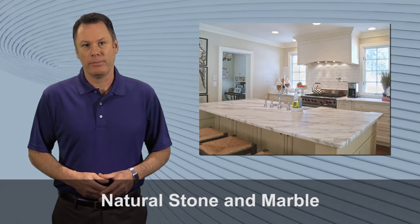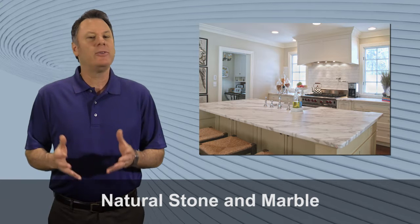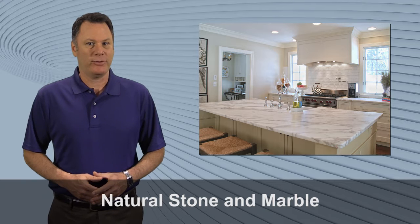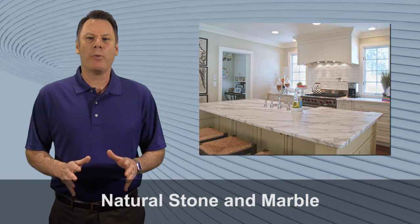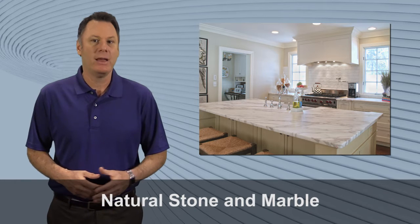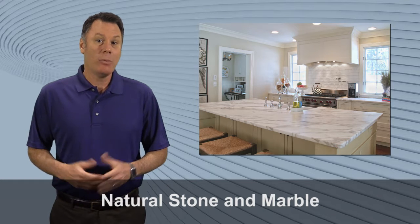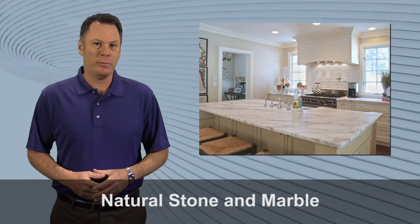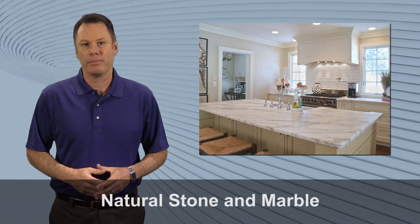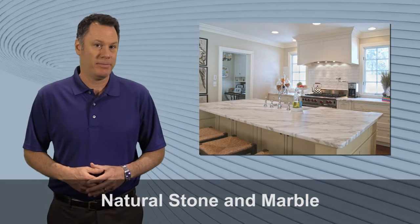Natural stone and marble. Natural stone and marble are great natural materials, combining beauty with design flexibility. They are available as slab and tiles and are heat resistant. Note that natural stone and marble are porous and can become stained even when sealed properly. In addition, seams can harbor bacteria and mold long before they are noticeable. While aesthetically pleasing, these types of surface materials can crack from impact and are considered difficult materials to repair. In certain applications, natural stone and marble solutions can be cost prohibitive.